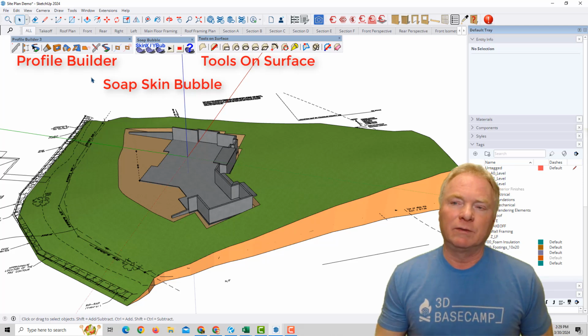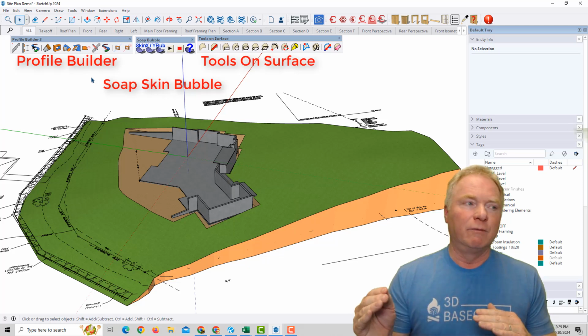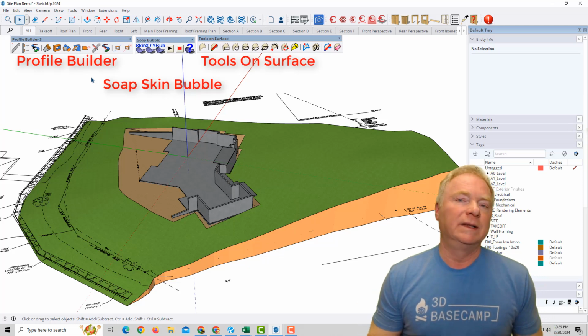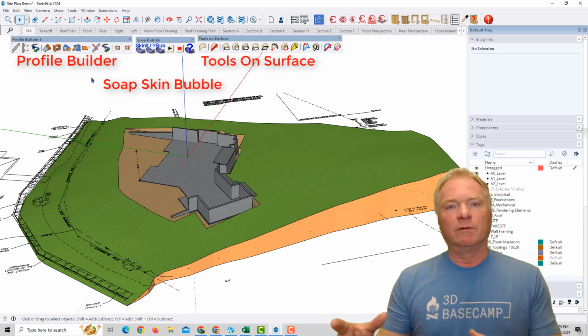You can use the sandbox tools, but it's going to throw a lot of extra triangles in there and a lot of really odd geometry that you end up having to delete out to make it a solid, because it's super important that we make these a solid so it reports a volume.